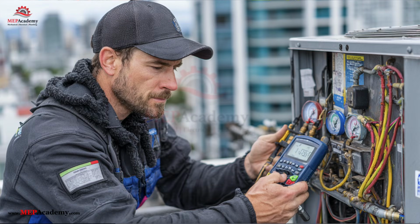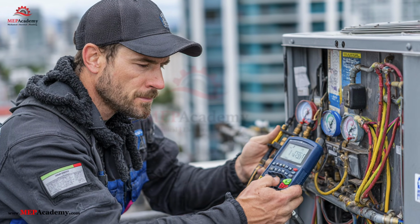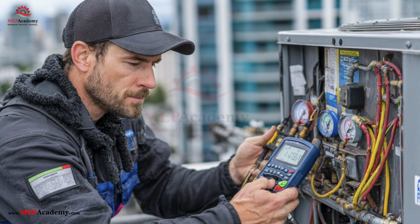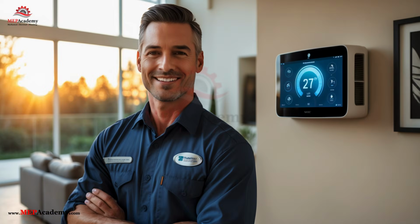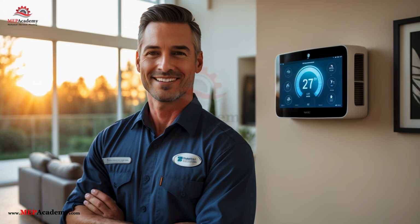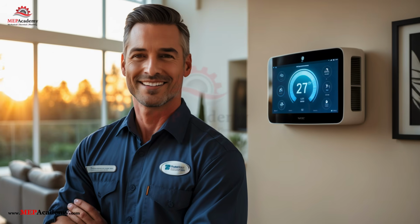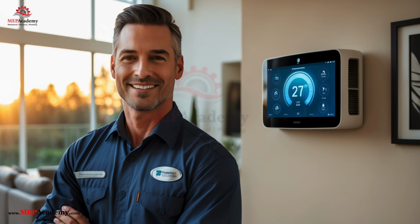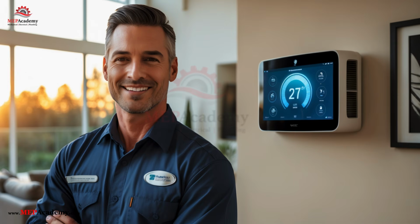Summary and takeaways. Low suction pressure is a symptom, not the problem. Whether it's a refrigerant issue, airflow problem, or restriction in the system, your job as a tech is to dig deeper and find the root cause. Check refrigerant charge. Inspect airflow and evaporator conditions. Test metering device function. Use superheat readings to confirm diagnosis.